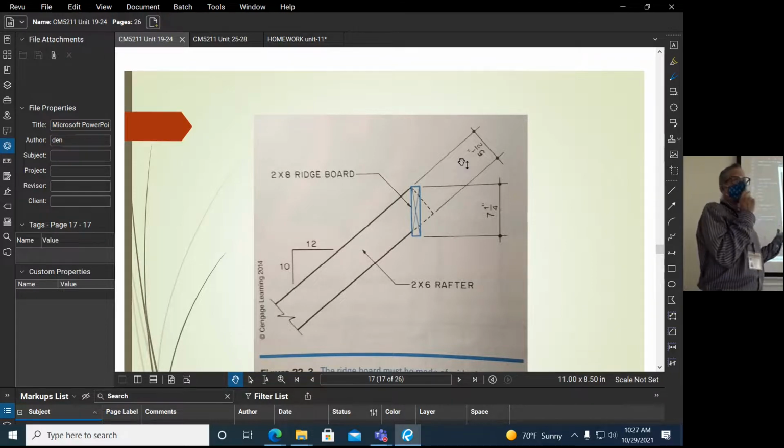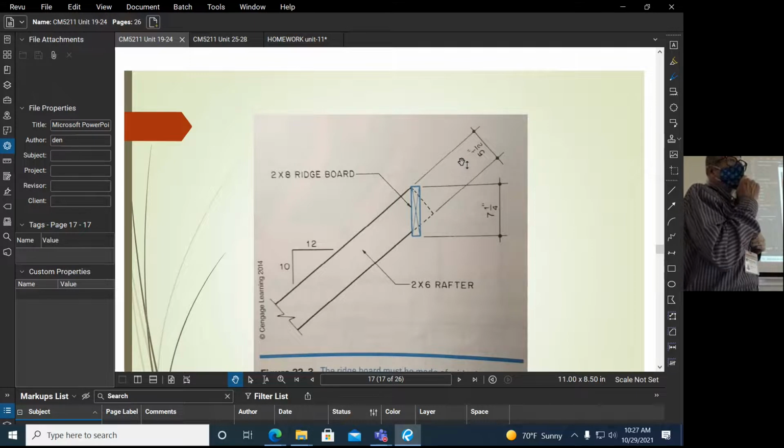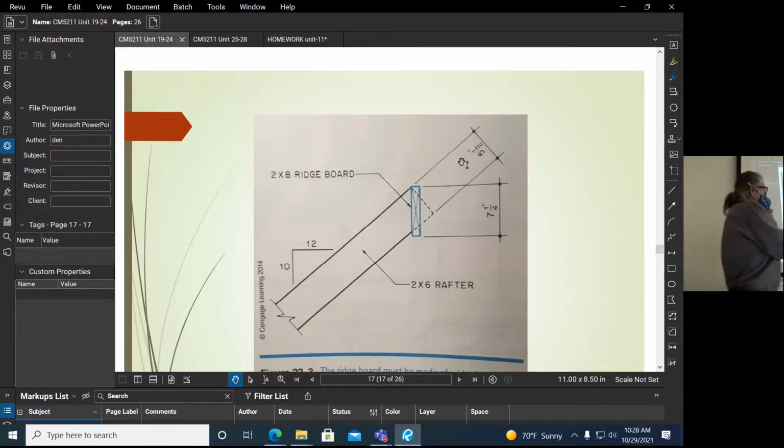You fabricate the trusses in a shop, and then you have them shipped to the site, whereas each and every rafter has to be fabricated in the field. So that's a lot of labor, and labor is a huge portion of our costs. It's more effective to have people build trusses in a factory, where they're building trusses all the time. They're really good, really fast, and really cheap at building trusses. Whereas carpenters are hard to find, and you need carpentry skills to make all of these various rafters, the ridge boards, and do all that.